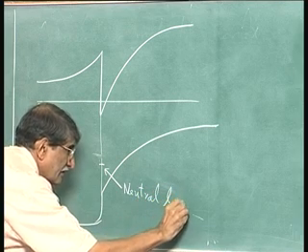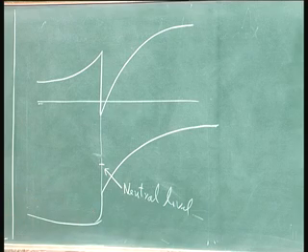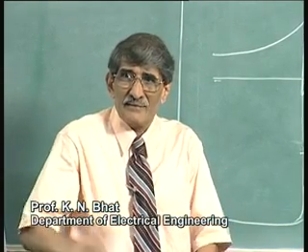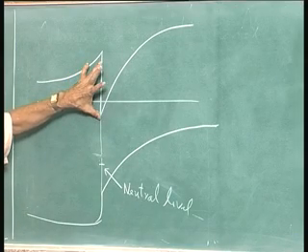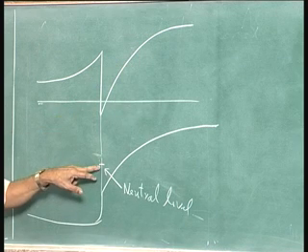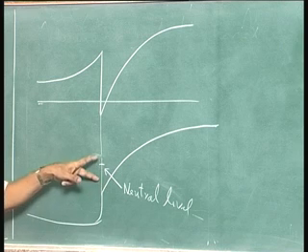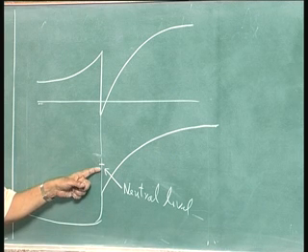What happens if they are not exactly equal? Now, the Fermi level is here. If they are exactly equal, this is actually the interface common to both. This is outside the band gap of this gallium arsenide. It does not see that really. It sees maybe in terms of this potential distribution. So here all these levels are occupied, because the Fermi level is above that. All these levels also are occupied. I am taking a situation where the neutral levels are perfectly aligned.